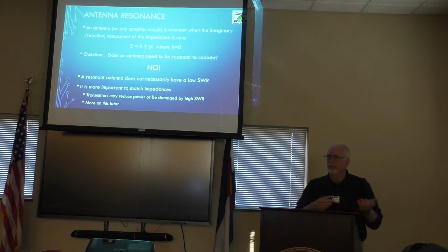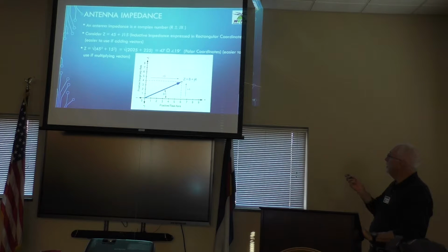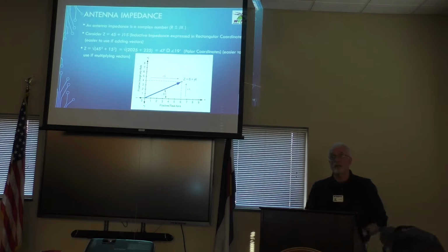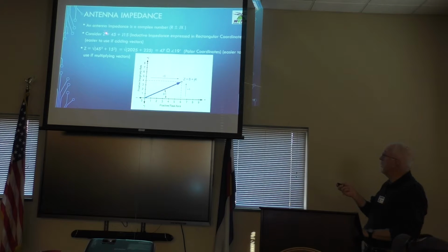No. I mean, they sometimes can go hand in hand, but that's not what people need to be thinking about. Antenna impedance is frequently expressed, and how many of you here have an antenna analyzer that will measure it? A lot of hands. So when you plug it in, turn it to the frequency that you're interested in, you will generally see a resistance with a plus or minus J. Well, on a chart, here's the resistance. This on the positive imaginary is the inductive reactance.